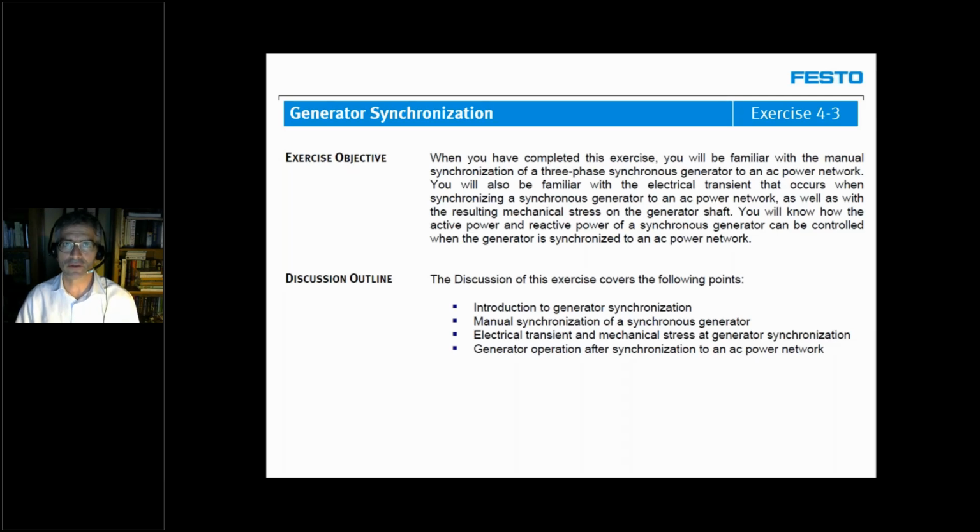So what is this? Well, first of all, you have to understand that whenever we want to connect a generator to produce power to push on the power grid, it has to be done in a specific way. For example, a hydropower plant may have 6 big generators, one beside another, that can be turned on and off depending on the needs. These generators are not all connected to the network at the same time. Depending on the needs, they will be connected to the power grid or not.